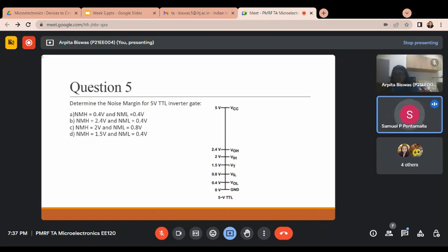The formula is there, madam. VOH minus VIH. Yes, just see here. Just a minute, I'm showing. Noise margin high is equal to VOH minus V input high. Here you can see the value mentioned. Just simply put the value, 2.4 minus 2, so 0.4 volt.